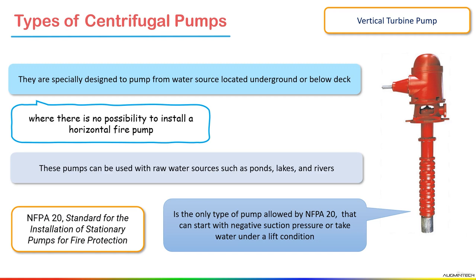As for the capacity and pressure available, the flow rate of this vertical turbine pump is a minimum of 50 and a maximum of up to 6000 US GPM, with a pressure rating of 2.76 to 26 bar. The speed rating is 1450 to 2950 rpm for the vertical turbine pump. So this is about the vertical turbine pump.